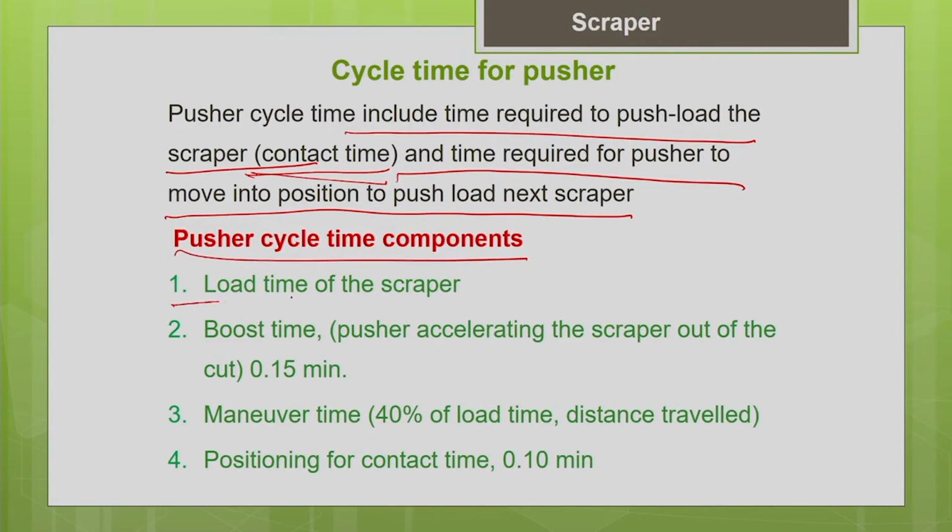Okay. One is the loading time of the scraper. And the other one is the boost time. The pusher will accelerate the scraper out of the cut. So that is called the boost time. Pusher accelerating the scraper out of the cut, say approximately 0.15 minute, can be taken as the boost time.